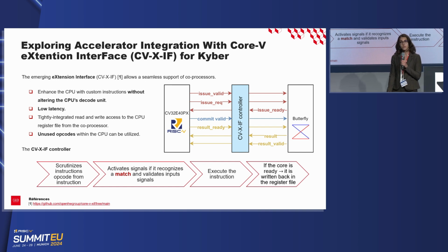That is a new interface that allows the seamless integration of a tightly coupled accelerator without any modification to the core and without any modification to the toolchain. It ensures extremely low latency because it is directly connected to the register file of the core, and you can add custom instructions by simply using an unused opcode of the core.